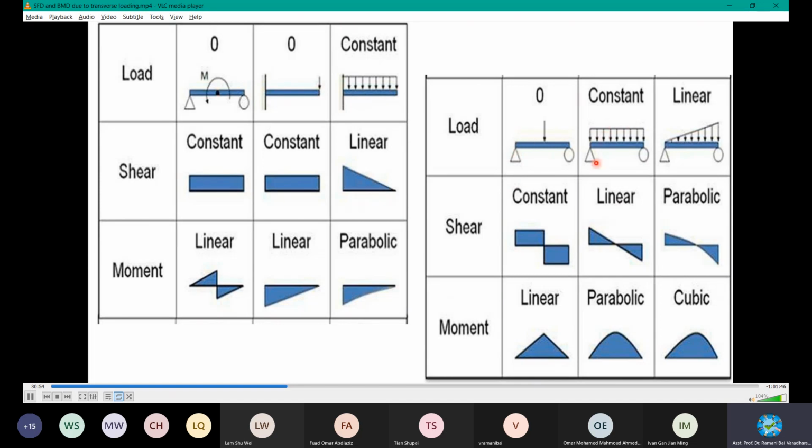Here there is nothing to balance out this reaction, but this reaction is balanced by this downward load. The balancing is slowly decreasing because it's totally away. The balance decreases to zero, and then it is increasing in this direction because it's towards another support. So it slowly increases as it reaches a reaction, upward and downward nearing.